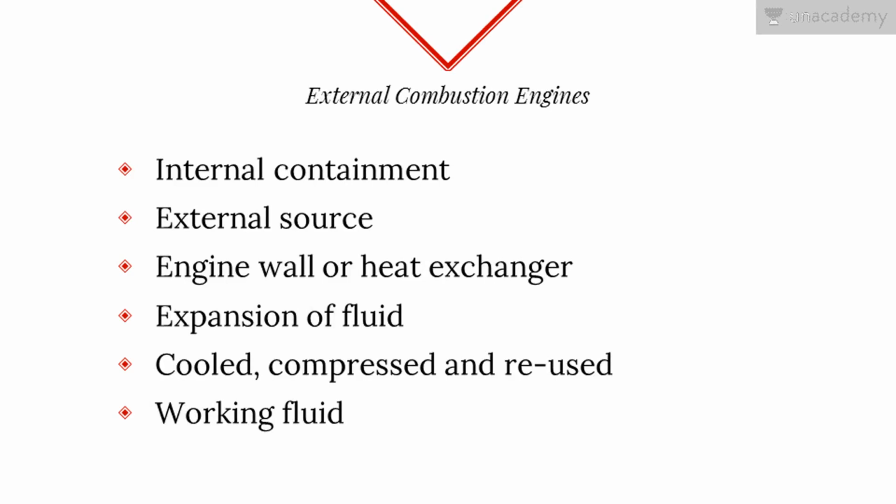So let's move on to external combustion engines. It is a type of heat engine where the working fluid is contained internally and it is heated by combustion in an external source, through the engine wall or through a heat exchanger. The fluid then gets expanded by the action of the mechanism of the engine and it produces motion or usable work. The fluid is then cooled, compressed and reused. That is nothing but the closed cycle engine. And cool fluid is pulled in.